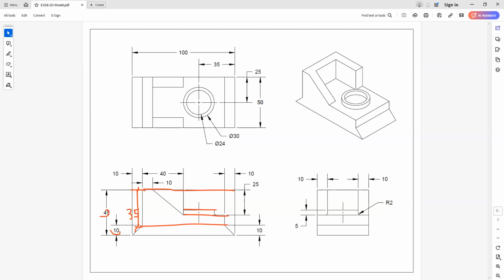The distance going to this line here is given to us almost, right? So we have a distance of 25, and that'll get me to this surface. But I need to get to this surface. Well, if I refer to this right side view, it says that it's 5 going from this face going up. So the 25 minus the 5, that distance should be set to 20, right? So we're looking at this drawing here. And that distance here should be set to 20.